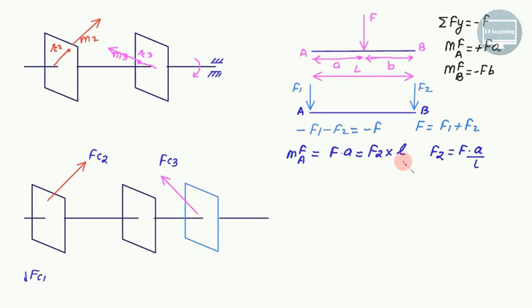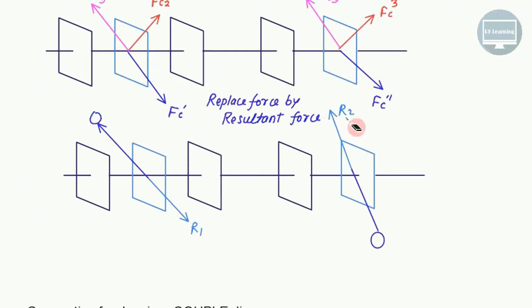So the idea is, can we divide one force into two forces? This system is the same as this system. The original system has been converted into two unbalanced forces, that is R1 and R2. To balance R1, we attach M1 at a certain radius equal to R1. Let's call this one MB1, RB1, and to balance R2, exactly in the opposite position, I will place MB2 at radius equal to RB2.